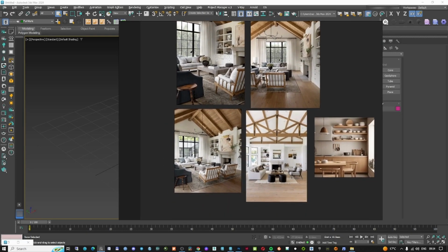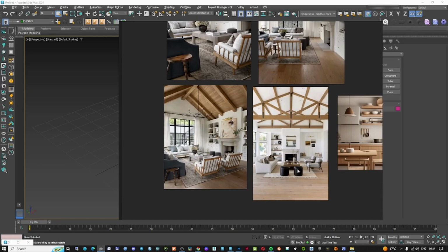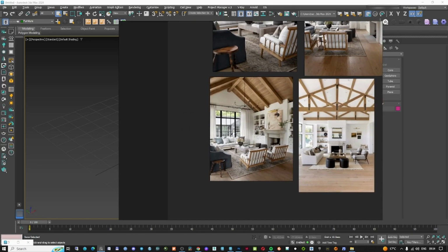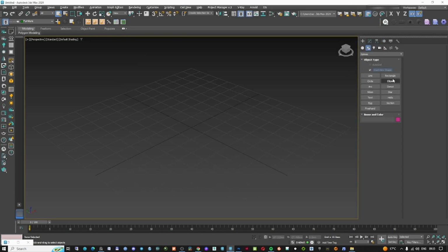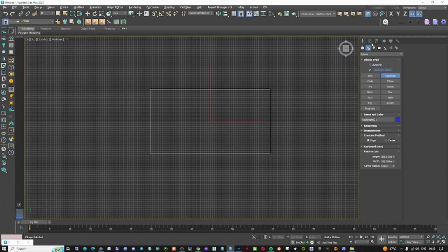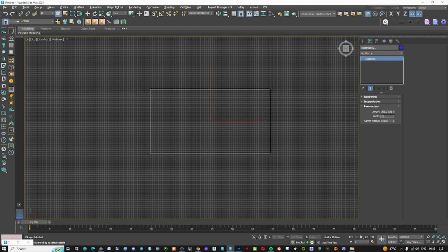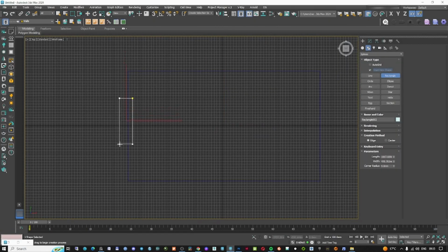So for now, I just need to know how big this room is, so I'm just going to make it 7 meters in that direction, as you can see, and in this direction I will just make it 4 meters for now. So let's see how everything looks. And for the height, the height is not too big, so I'm guessing that if this is a door, this is 45 with another 45, 90, 180, so this is like 220 maybe, something like that. So yeah, let's start. I will just make a rectangle, go on my walls on the top part, and here in the middle I will just create it fast. So in this direction I set 7,000 by 4,000.